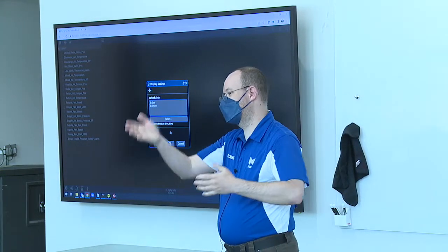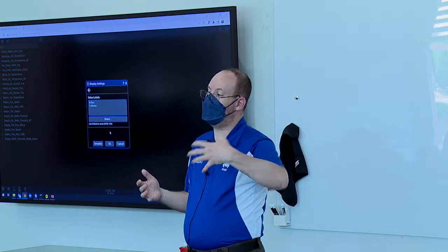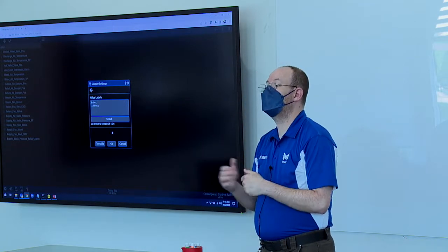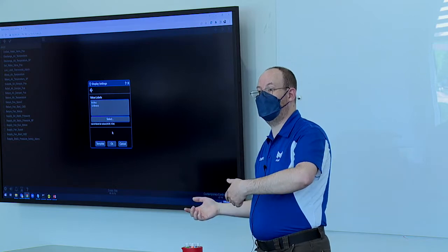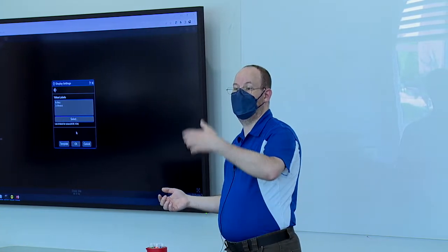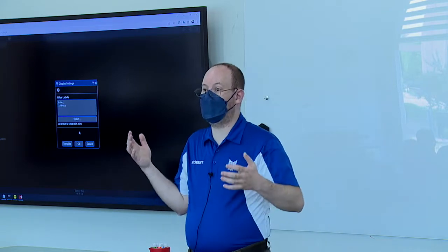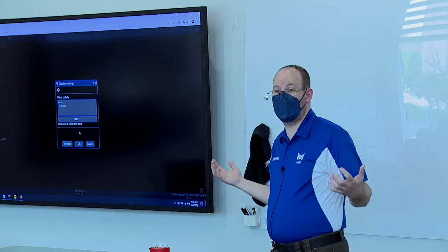Assuming no further outside influence, if we lose power to the outside air damper, what should happen? It should close. Spring return close. It depends on what type of damper control you've got on it. You've got a spring return or you don't have a spring. Fair enough. And largely that's going to depend on what the device is and where in the country you are.